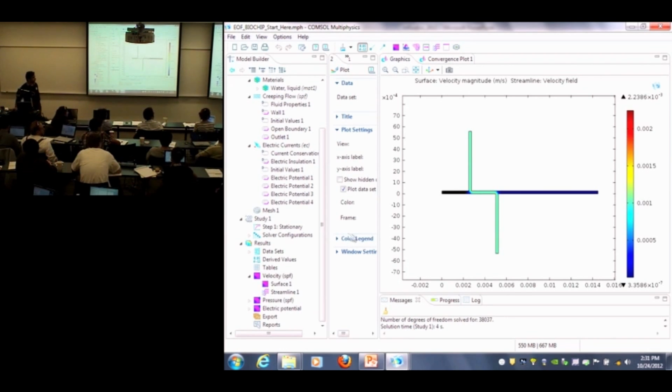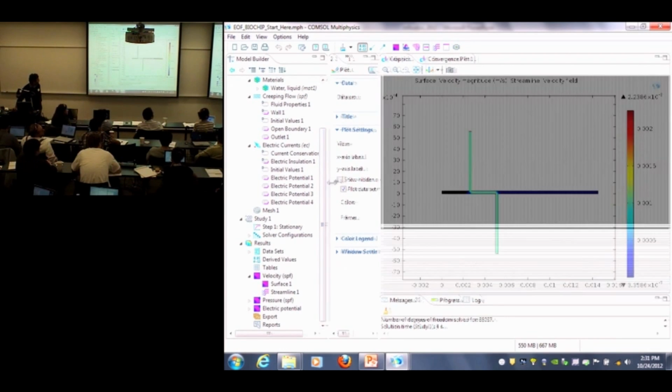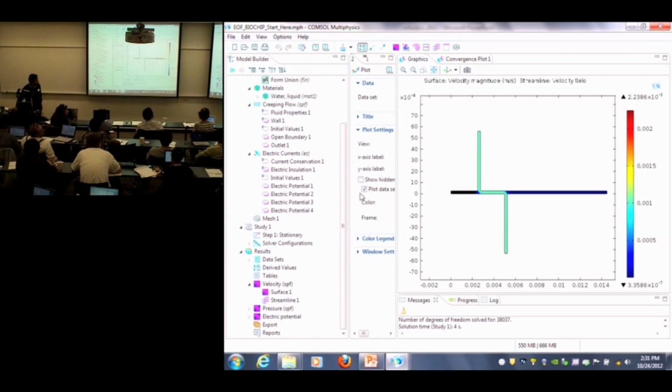Your calculations are based entirely on the properties of the water, right? Yeah. So you're assuming that whatever's in the water is going where you want it to go. Yeah, it's just the fluid flow actually. So if you have certain species, you add another physics to it. Like if you have a species A or a species B, then you use the convection-diffusion equations, and you couple the fluid velocity with that convection-diffusion equation.